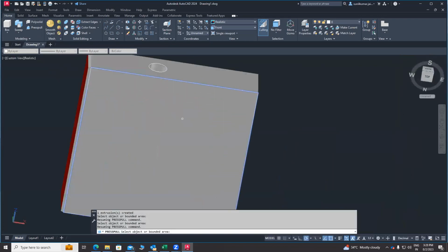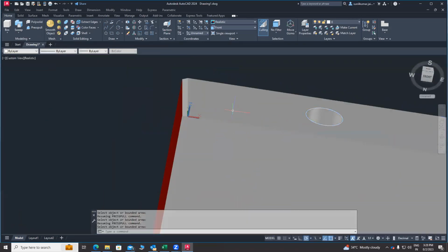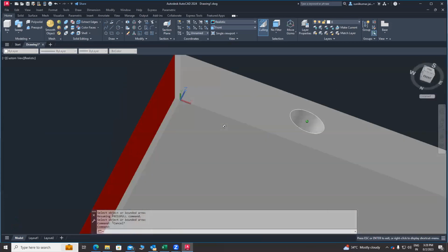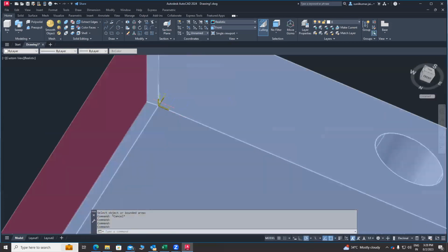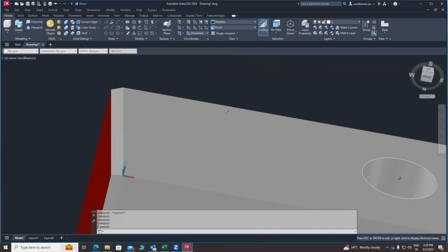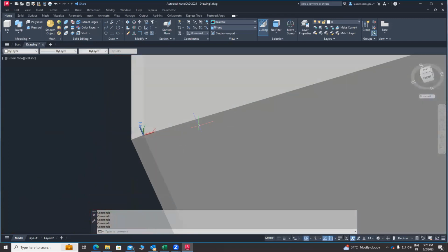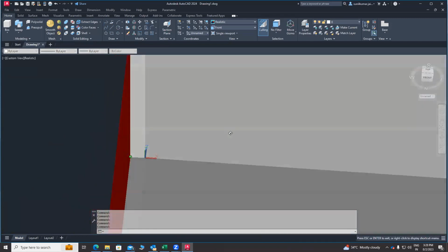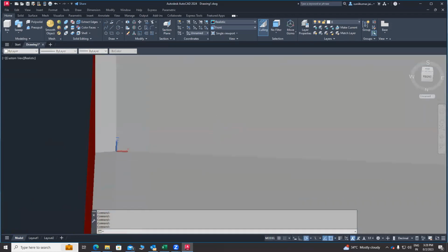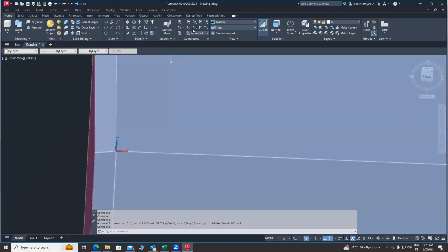Okay, if we want to cut, because the XY plane is my 2D sketch plane. So if we want to change the coordinate to any angle, we have the XYZ rotate option. So go to the XYZ rotate option.